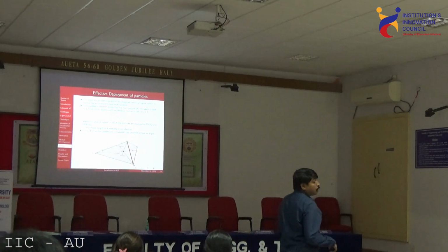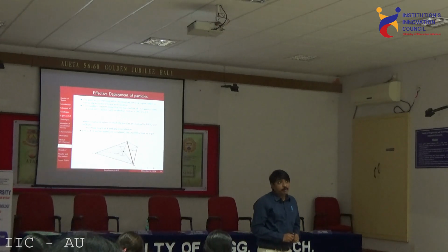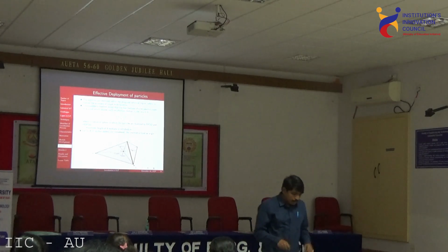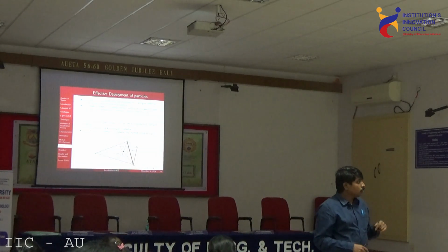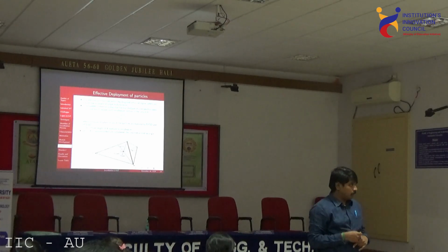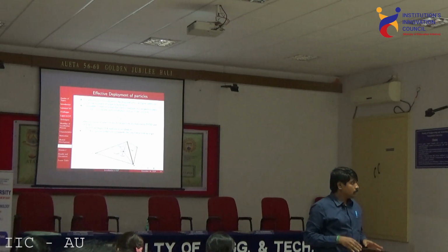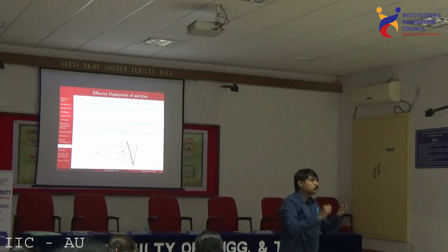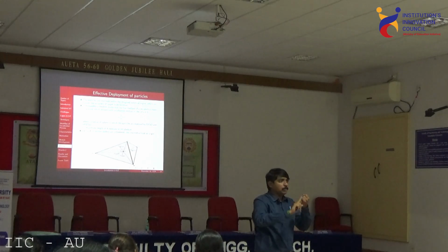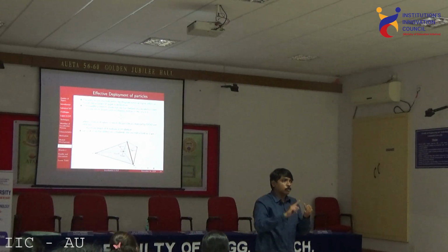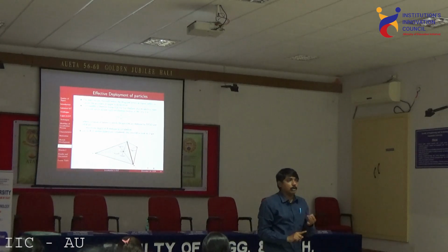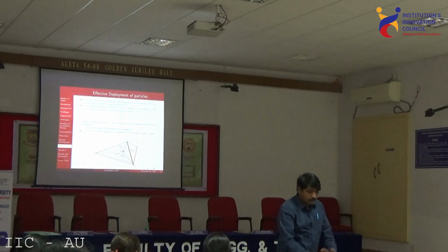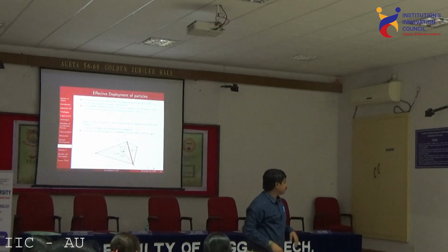Now, coming back. I need to find the shortest path for communicating this problem from this location. Because I found that at this location the temperature is very high, I need to inform my server that there is an abnormality here. I should not take the longest path, I should take the shortest path so that this data is sent over there. So this is the third criterion. The first criterion is knowing the location of an unknown node. Second, the known parameters are only D1, D2, and D3. And third is the shortest path, or how quickly I can transfer the data from here to there.